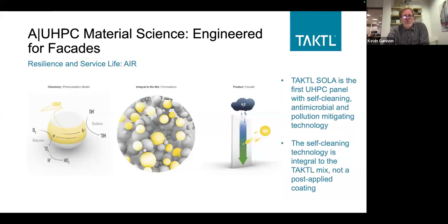And then we've also got, we mentioned before, a photocatalytic material. UHPC is very well suited to this because it does not degrade on its surface the way other concretes do. And the degradation of a normal concrete would prevent the chemical reactions taking place, whereas UHPC surface does not degrade. So it will continue for the life of the panel to be able to be activated.